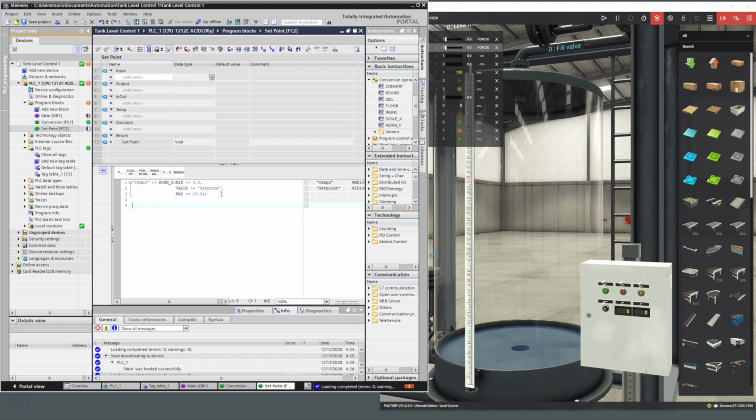So we can now scale temp2 using the ScaleX instruction from 0 to 300. So SP real is equal to, and bring down a ScaleX, and min is 0.0 and max is 300. Then the value is temp2 and we'll add a semicolon at the end. Okay, we'll tidy up the code again.